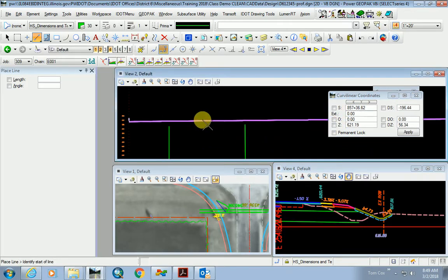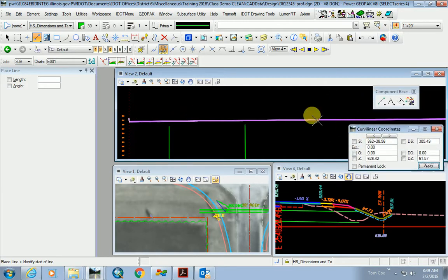So just like designing a roadway profile, you always have constraints that you're working in. I know I need to get from here to here. Now, what's that going to look like? And you almost always start off, well, what happens if it was just a straight line? What's my percent going to be, my grade?